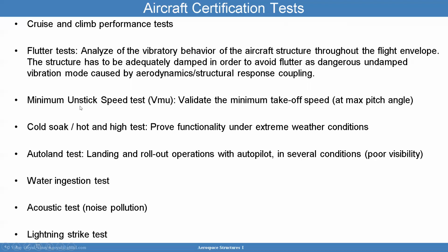The minimum unstick speed test needs to be performed. It's to validate the minimum takeoff speed at maximum pitch angle. The cold soak and hot high test needs to prove functionality under extreme weather conditions, where, for example, you're going to Alaska or very cold conditions like North Russia. In those areas we need to make sure that these aircraft can do a good job in hot and cold conditions. For example, landing in very hot conditions or taking off in hot conditions.